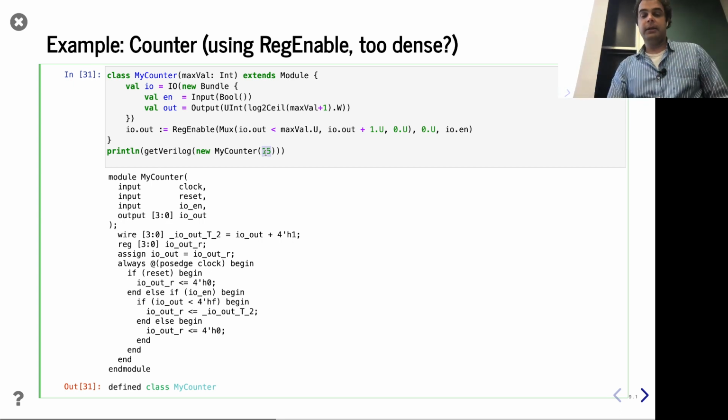There are some utilities built into Chisel if you would like to use them. For example, a common one is log2Ceil, which, if given a number, tells you that number taken log2, rounded up to the nearest integer. In this case, this is what we need, right? We want to know how many bits it is going to take to hold this thing. How many bits would it take me to hold 15, for example? We're going to see, oh yeah, that takes 4 bits, so it's 3 colon 0. So we're going to size that thing appropriately. Cool. Questions?